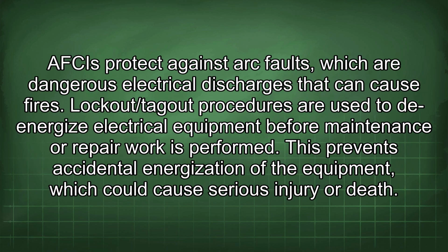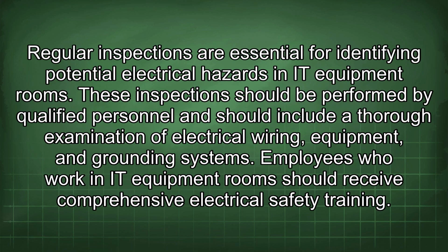AFCIs protect against arc faults, which are dangerous electrical discharges that can cause fires. Lockout/tagout procedures are used to de-energize electrical equipment before maintenance or repair work is performed. This prevents accidental energization of the equipment, which could cause serious injury or death. Regular inspections are essential for identifying potential electrical hazards in IT equipment rooms.